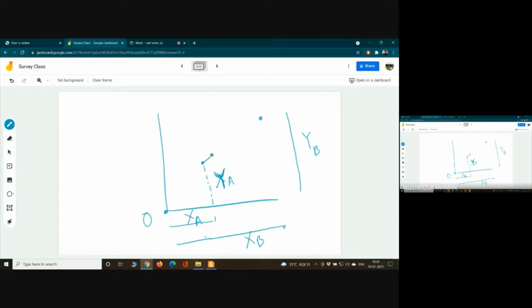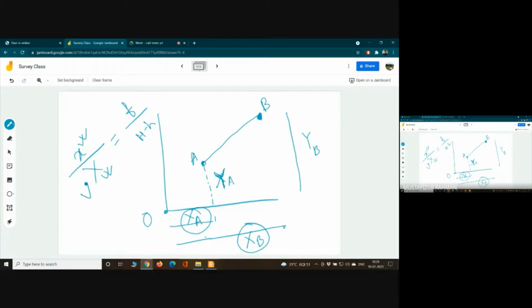Now we need to find out what is this distance. So for that we have the formula, right? And these values can be found from the photograph coordinates. If the photograph coordinates are given, so if we write capital X by small x, this is what? This is the map distance or photo distance to the original distance. So this is nothing but the scale of the photograph. So using this, we can relate the actual coordinate to the photograph coordinate. And then we can find out the distance between these 2 points.